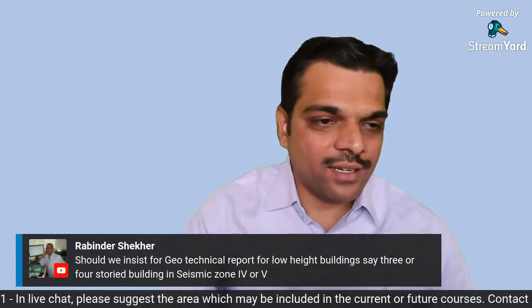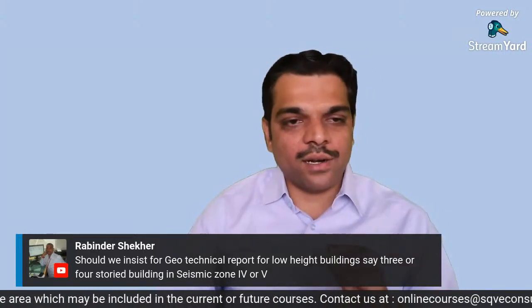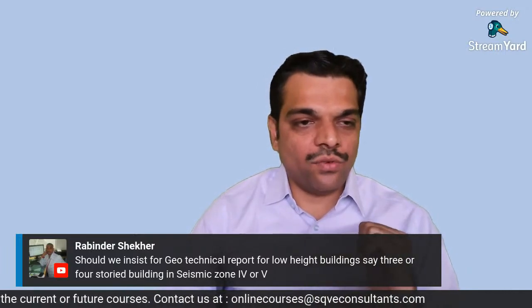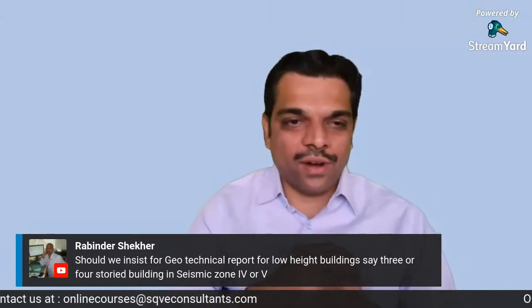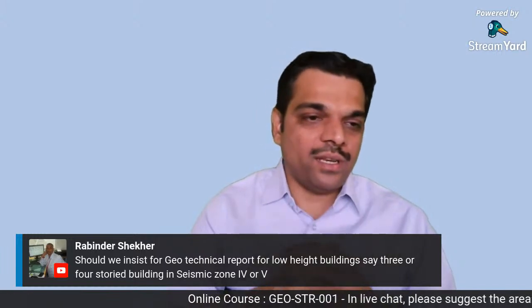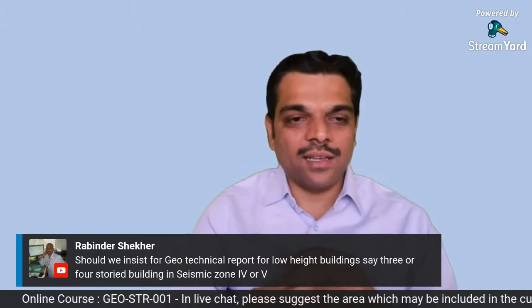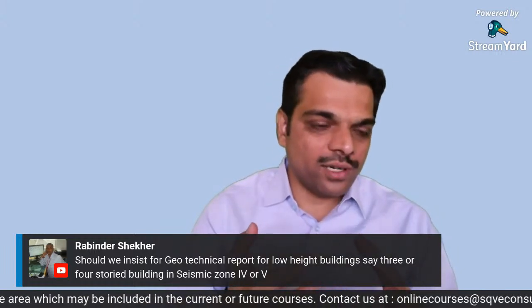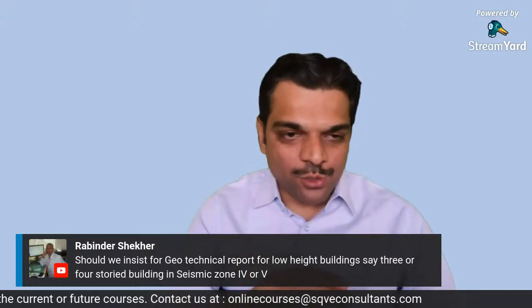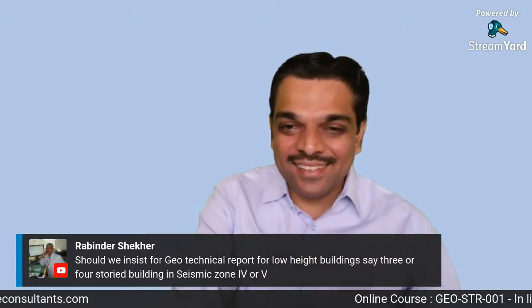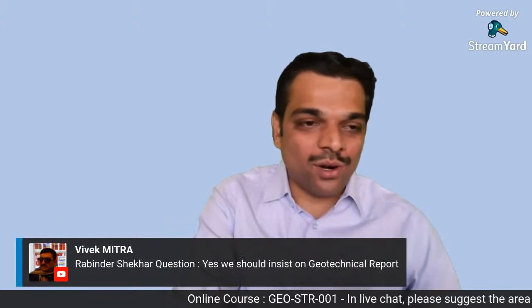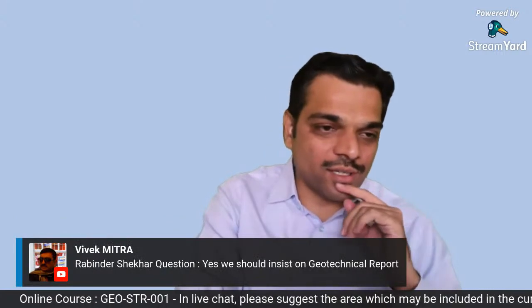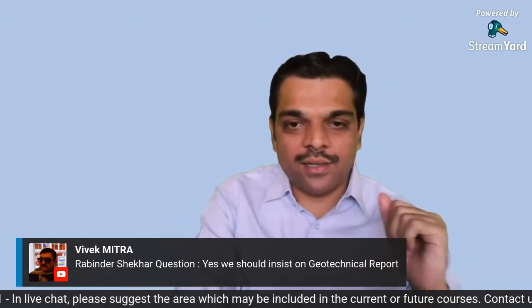Okay, Rabinder Shekhar is asking, should we insist on a geotechnical report for a low height building, say 3 or 4 storied buildings in seismic zone 4 or 5? Yeah, very interesting question. I'll let Vivek Mitra respond to it. See, in my opinion, we should insist on a geotechnical investigation report even for a low height building, because you're already telling it's a 3 or 4 storied building, and the seismic zone is 4 or 5. So in my opinion, definitely the soil investigation should be there. Yeah. So Vivek Mitra's point of view on that question is, yes, we should insist on the geotechnical report, right?